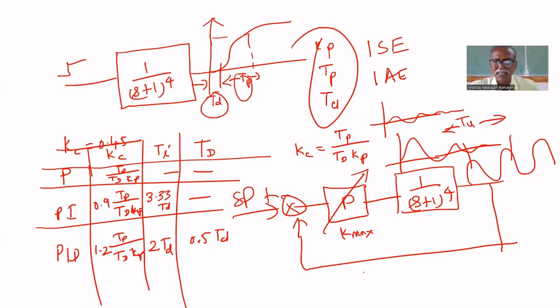If you integrate by taking absolute error, positive stays positive and negative becomes positive, and you get the area under the graph. Similarly for the other one. Which area will be higher? The second graph. Therefore, ISE and IAE must be minimum for a better controller, so analytically you can find which one is the best controller.